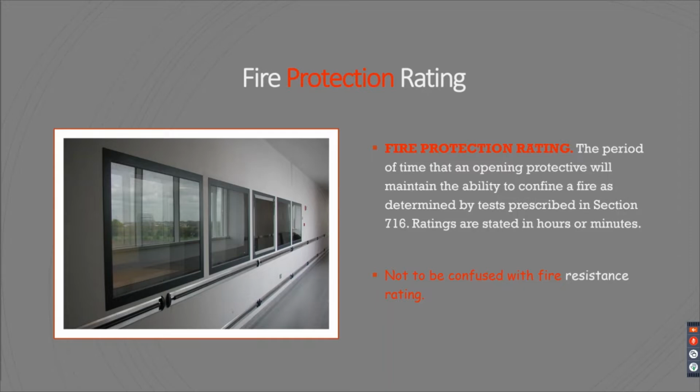So then what's fire protection rating? The fire protection rating is the period of time that an opening protective will maintain the ability to confine a fire as determined by tests prescribed in 716. And then ratings are stated in hours or minutes.